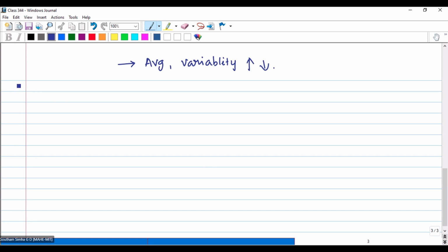Now we'll go to the core mathematical part. Consider the signal that is received at the receiver. I'll write it in terms of yi, that is equal to hi, where H is the channel matrix, into the signal s plus noise, additive white Gaussian noise, ni. Now i is equal to 1, 2, 3, 4 up to say L number of branches or MR number of received branches.